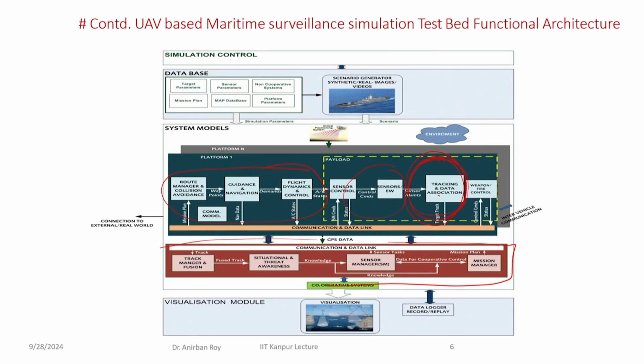So, using the payload information, it is coming to the ground control station. In the ground control station, you have deployed, suppose to monitor the target, your radar, your UIR, or primarily these two sensors, plus you could have something coming from GPS as well, some satellite information also. You fuse everything here. Once you fuse this information, you have two major blocks.